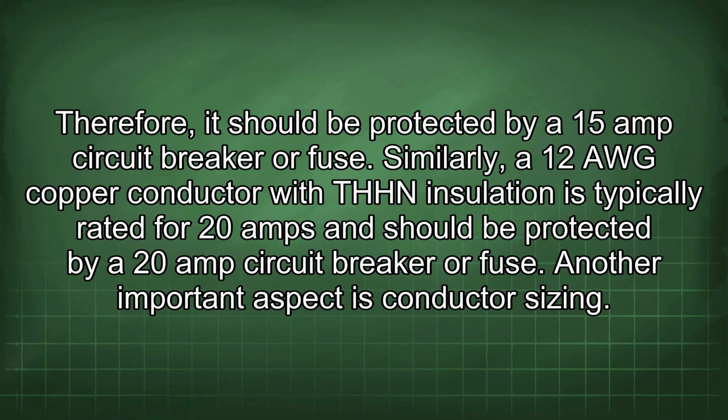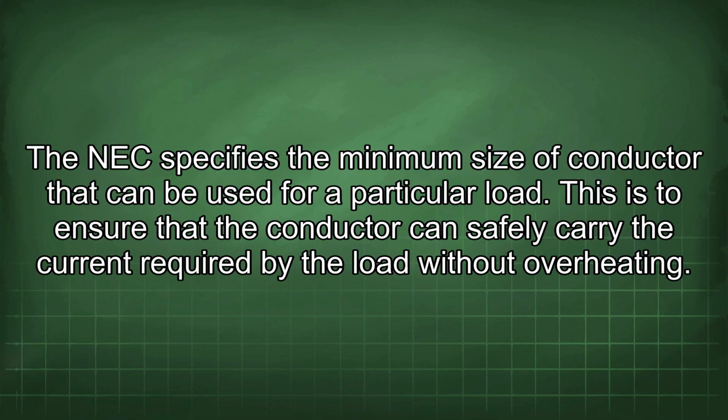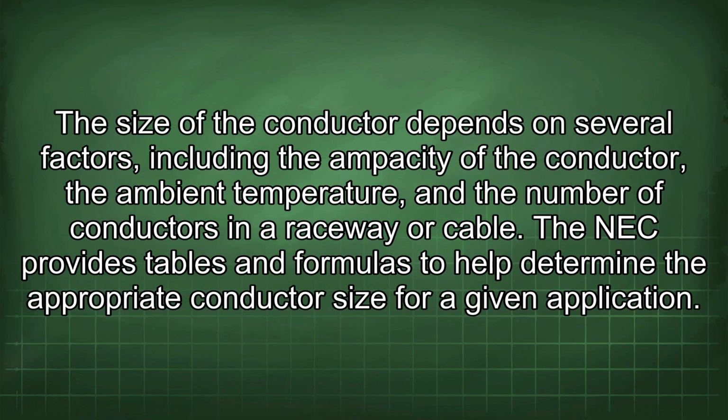Another important aspect is conductor sizing. The NEC specifies the minimum size of conductor that can be used for a particular load. This is to ensure that the conductor can safely carry the current required by the load without overheating. The size of the conductor depends on several factors, including the ampacity of the conductor, the ambient temperature, and the number of conductors in a raceway or cable. The NEC provides tables and formulas to help determine the appropriate conductor size for a given application.